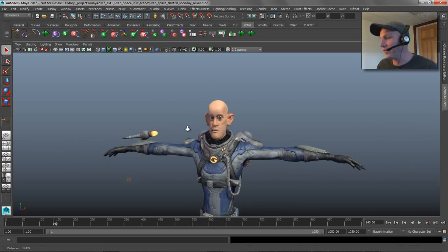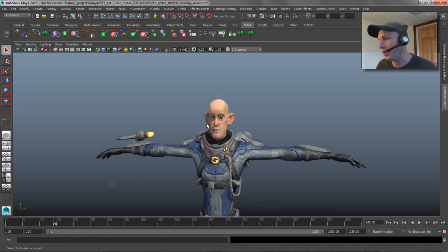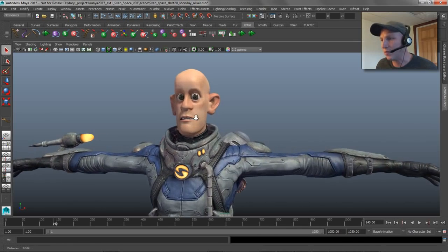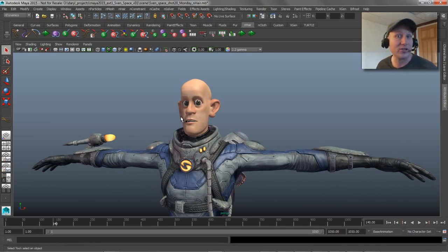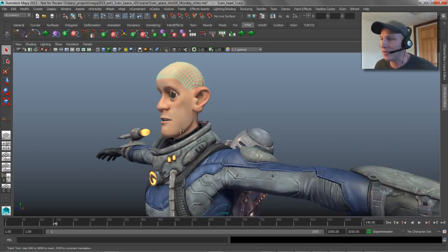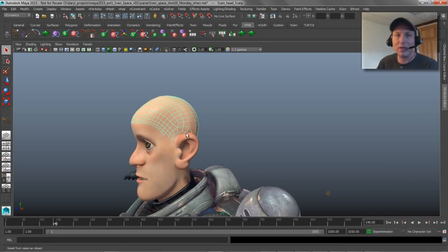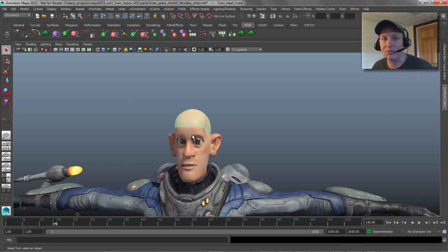So this is Maya 2015, which means Nhair now shows up in Viewport 2.0, which is awesome. So we'll be using this Sven character that was originally put together for some of the launch demos to talk about Nhair today. I've got a piece of geometry inside of here that was just a duplicate of this guy's head with some faces deleted that we're going to use to emit some hair from. So what we want to do is just grow some hair off of this guy, relax the hair, and once we get into a nice relaxed state, set that as our start and current position that the hair tries to start from and maintain. So it's a pretty straightforward workflow, and I'll show you some of the things that are inherently wrong with it as we go along the way and how to work around those.